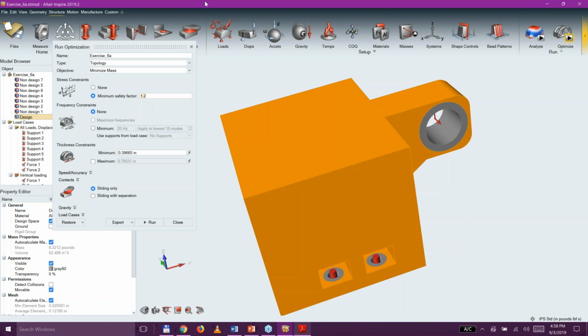So as the optimization code begins to remove material to minimize that mass, stress is going to increase in the part. Less material to handle the force means higher stress in the part. So now, just like before, it has to very, very carefully and intelligently select the best material to remain to make the part as light as possible, but adhere to this safety restriction.